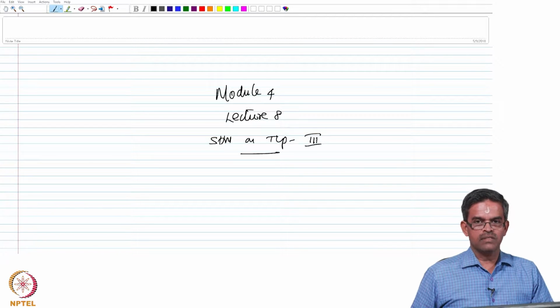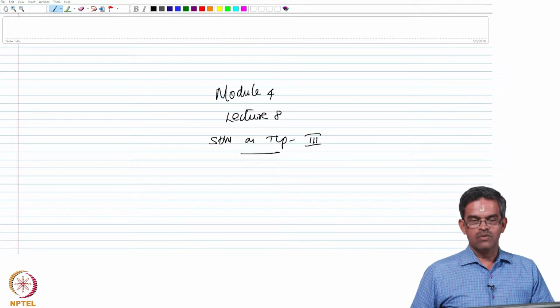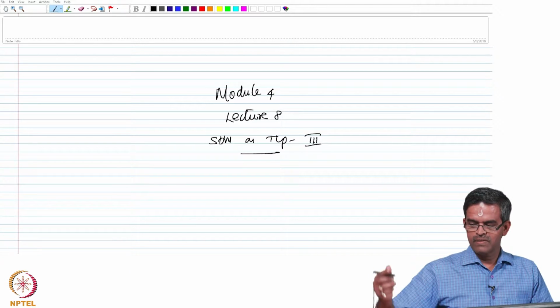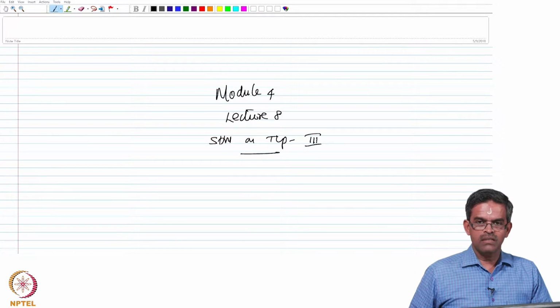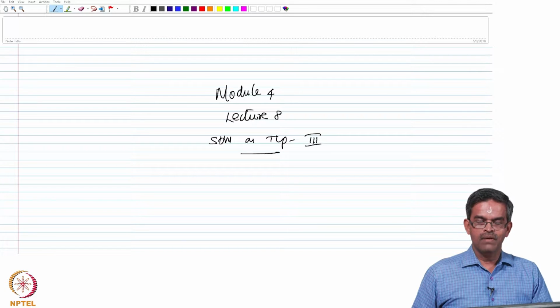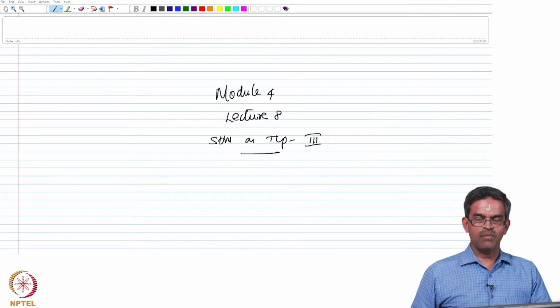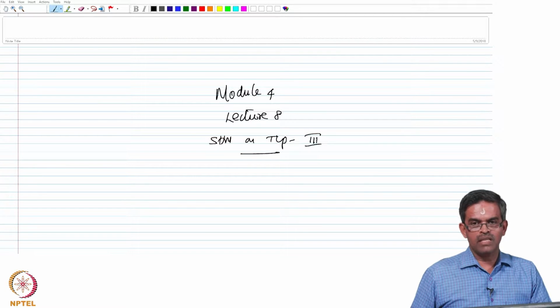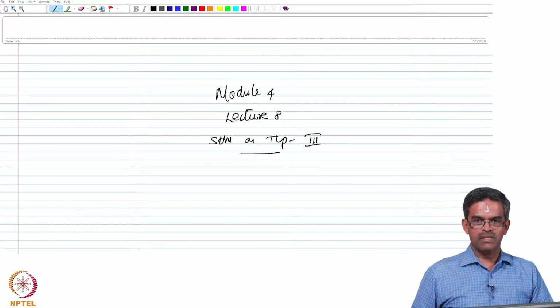We are going to talk about the design of a structural health monitoring system which has been done on the lab scale to investigate the damage analysis of a tension leg platform which is being subjected to postulated failure. As such, the TLP has not failed in the lab; an intended failure has been caused on the TLP model, and we are now designing a structural health monitoring system and an alert monitoring system to see whether the proposed SHM is capable of diagnosing the defect which has happened on the failed model, and is it able to communicate the failure to the user client server as required through SMS and email, etc.